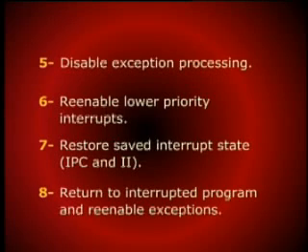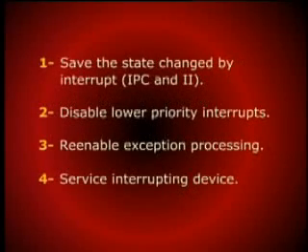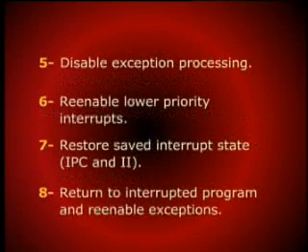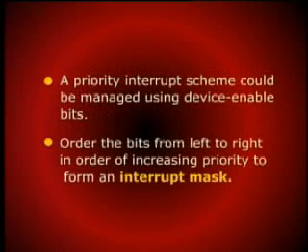Much of the implementation in a nested interrupt system is a matter of software design. However, there are places where hardware support would make the system more efficient. Steps 2 and 6, which mean disabling the low priority interrupts and re-enabling the low priority devices, may take a lot of time. And if it is done through software, the overall structure of the program would be slower. Hardware support for this priority disabling would be desirable.